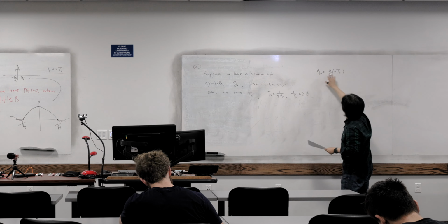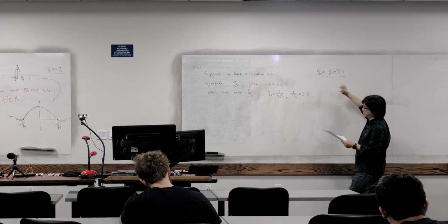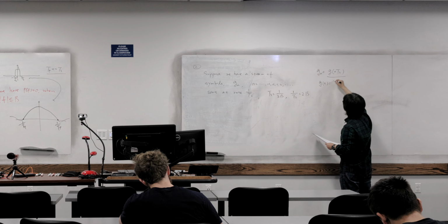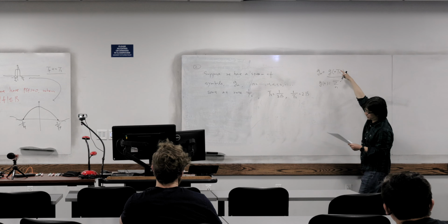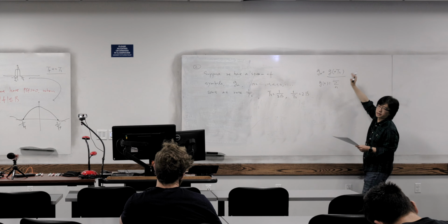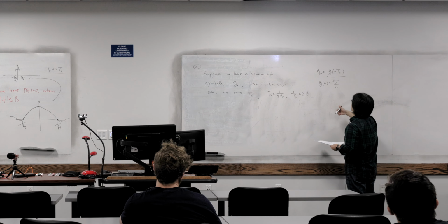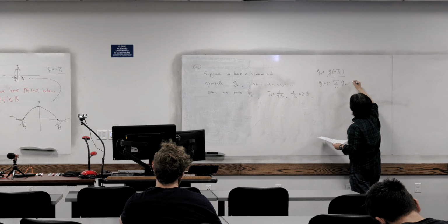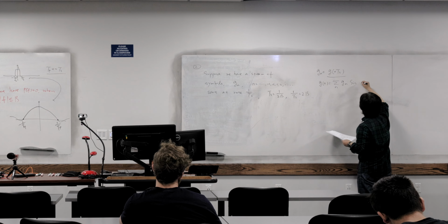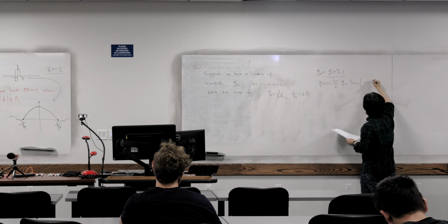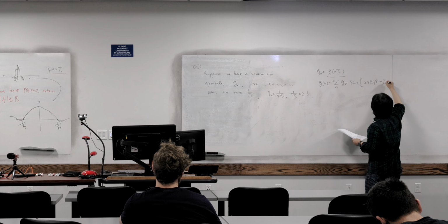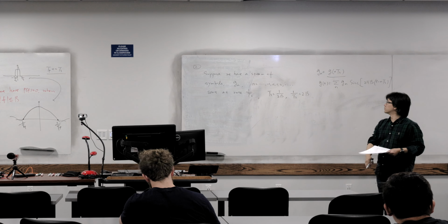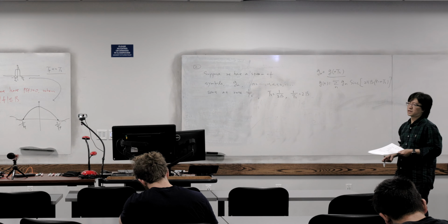Gn is a sampled signal of this one, and equivalently, we can write G(t) as a sum over Gn weighted and multiplied by the sinc signal, as the original ideal reconstruction. So you can write this as Gn multiplied by the sinc interpolation. We assume the ideal interpolation here, which is the relation to what we have discussed before.